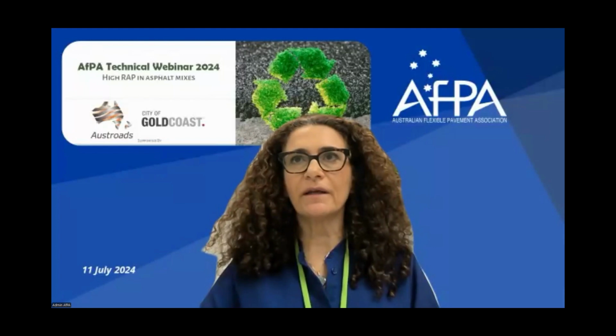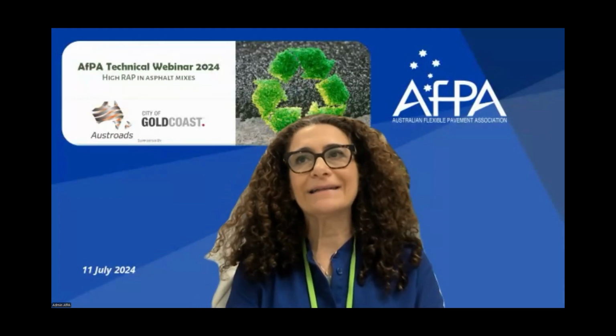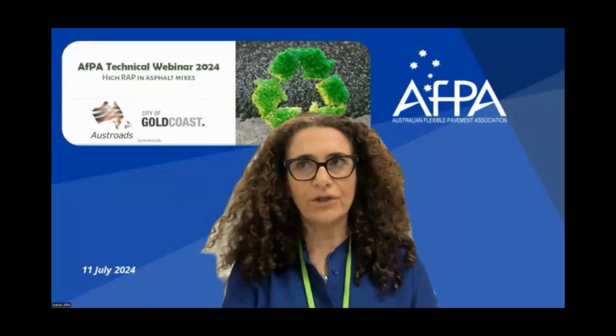So thank you. And do you want to add anything around that comment on the rejuvenators, that they function as a softener or alter the composition of the aged bitumen? Yeah, I think that's true. It's hard in the compact time slot to dig into the asphalt chemistry specifically, but there's SARA analysis people use to look at that, and then trying to understand the aging of the binder.